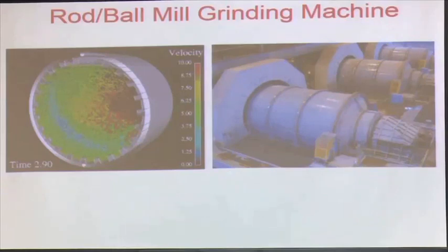Suppose my RPM is very high, then the entire material will be rotated and there is no breakage. That is called the critical speed. There is some calculation, but we are not going to deal with that in this lecture. So, we allow them to fall freely. Which one will be carried further? That is the particles which have more mass. Normally, the steel balls will be coming down at a later stage.